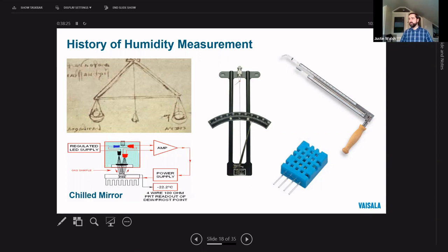And now, demand continued for more accurate and full range relative humidity measurements in weather and research applications, and a more accurate and low maintenance solution was needed. After the invention of the transistor, the first electrical humidity sensors were developed. These sensors were based on measuring the electrical resistance or impedance, as materials would absorb water vapor and their resistance characteristics would change accordingly. These sensors did work fairly well, but also had their drawbacks such as poor stability, limited accuracy, and difficulty responding quickly to decreasing humidity levels, which is also known as hysteresis.